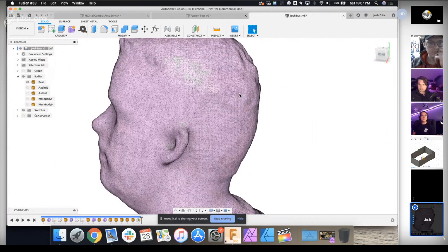Okay. I think if you were to try to input a model and use it, it'll tell you, I think it's like 10,000, but I think the real number is 20,000 facets. So you kind of have to low poly it and dumb down an external STL so that Fusion doesn't freak out and crash. And if you want to alter it in any way,